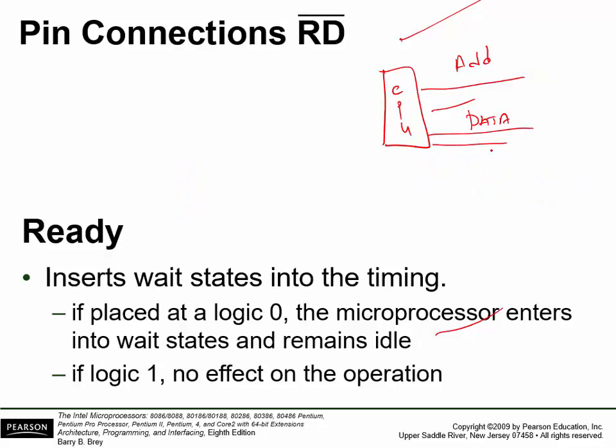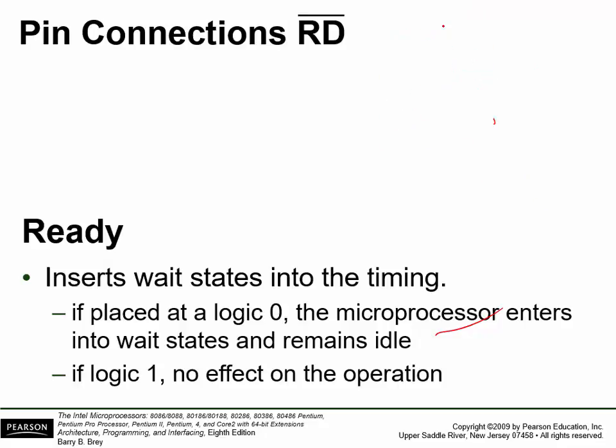I've used DMA for accessing a lot of the early hard drives, because if I want to load a bunch of data from the hard drive to memory, it's quicker to have the hard drive controller talk to the memory directly and not go through the CPU. So you would put the processor to sleep. It's one of those things we talked about because it was very common back in the 1980s, even into the 90s. With so many pins available and the speeds these processors operate at, we typically don't do it much anymore.